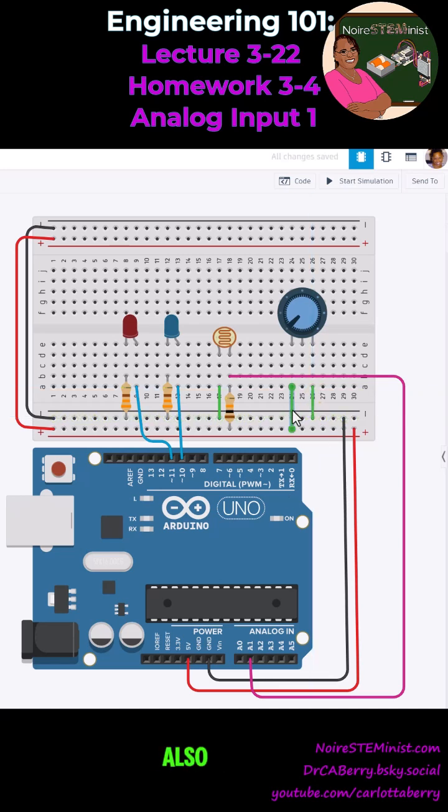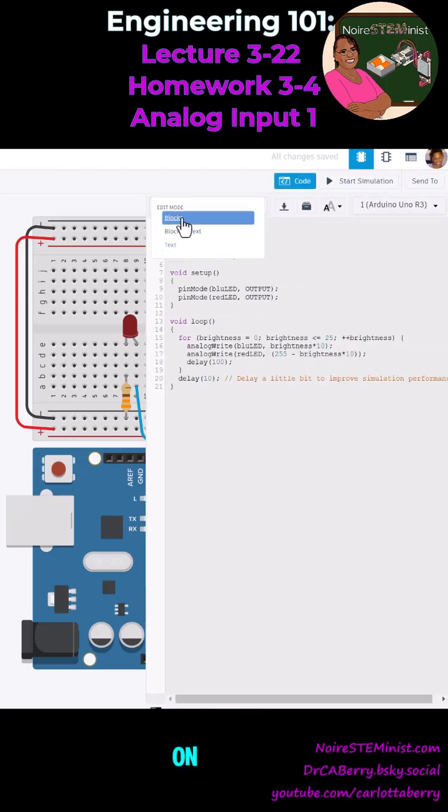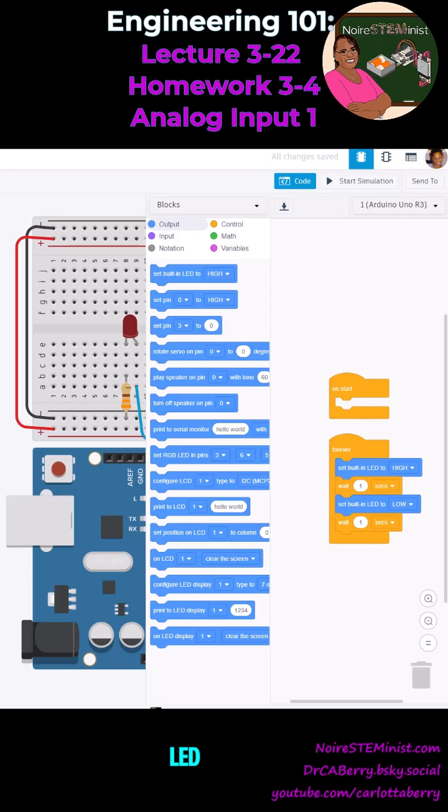And then I'm also going to attach a 5-volt and ground to my potentiometer and attach that middle pin to A1 so that that's also an analog input, and I will show you how I can use both of these analog inputs to vary the brightness on my red and blue LED.